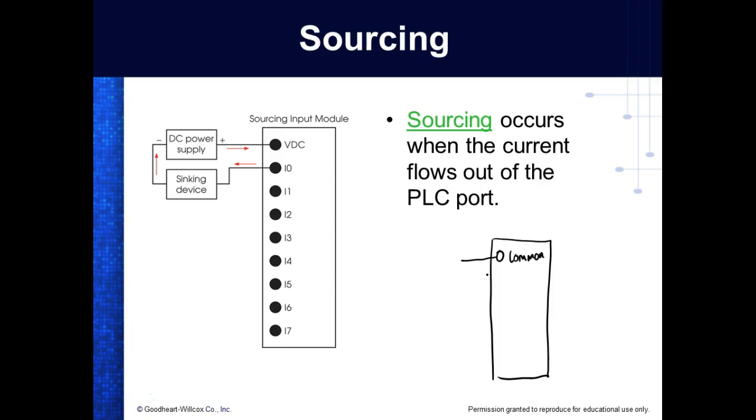And the problem in DC, we think about our cars and stuff like that, and your car runs a minus common. So a lot of people think that common's got to be minus all the time, but that's not true. In fact, we can share common between power supplies. So this could be a plus, and this is the way your trainer does, by the way.